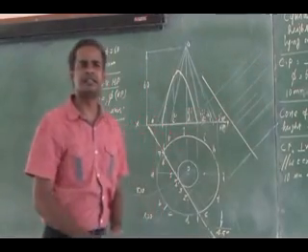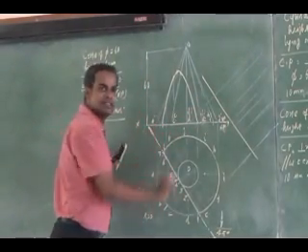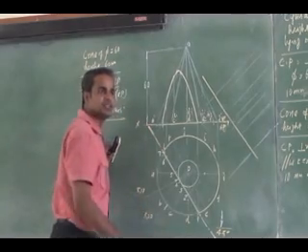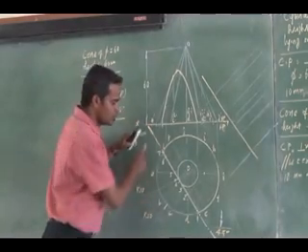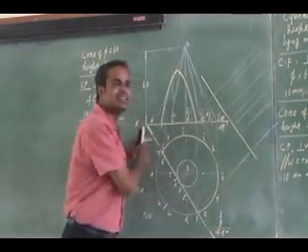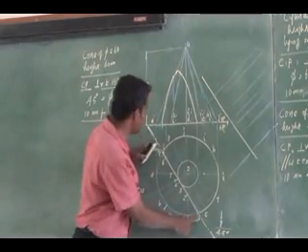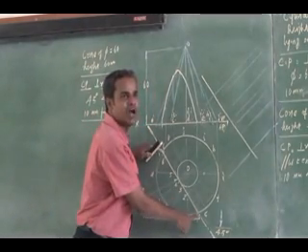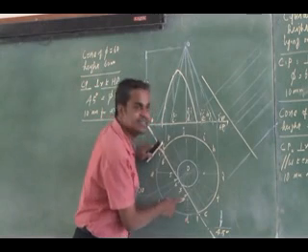Listen all of you. Listen. This problem as it is drawn, cutting plane is represented in the top view. So you see here, it cuts the base. So base, I will have two cutting points, 1 and 7 on the circle. Then it cuts the generator.